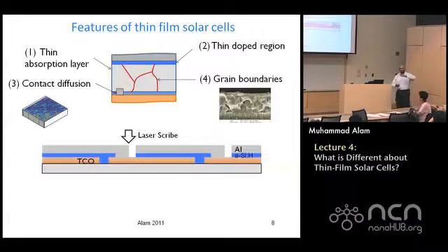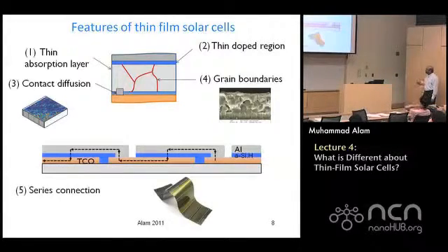Instead of having a simple P-I-N junction, these successive layers of things, now currents are going to do this. It will enter through one end, go up through this contact, come down, so this is one solar cell. Then go down, come up, and again come down, that's another solar cell. And so, although initially you had a thin planar structure, by scribing and connecting it up properly, you have just made it a series of solar cells which are connected in series.